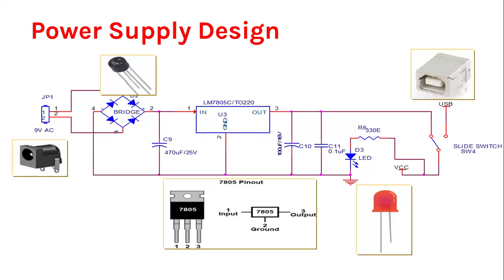Red color requires 1.8 volts to 2.2 volts. For conducting, 1.8 is required, and the maximum voltage is 2.2. Remember, guys. Green, 2 volts to 3 volts. Blue, 2 volts to 3.5 volts. White, 3 volts to 3.5 volts. So in the worst case, the requirement is 1.8 for conducting. Some of the different colors have different requirements. Okay, did you understand, guys?